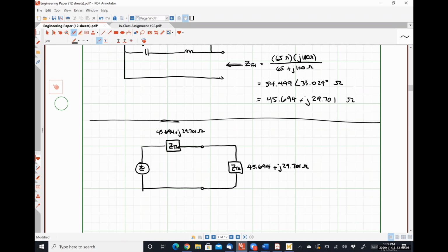Thevenin equivalent circuit is just a practical voltage source connected to our load impedance. Norton equivalent circuit is just a practical current source connected to our load impedance, and it's going to make our power analysis on our load very, very trivial to do. So we need to make sure to divide our Thevenin voltage by the square root of 2 to get into the RMS phasor domain where we can apply our complex power relationships.